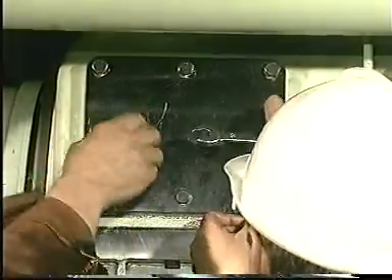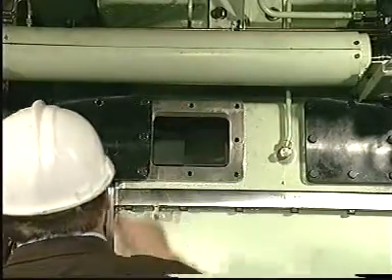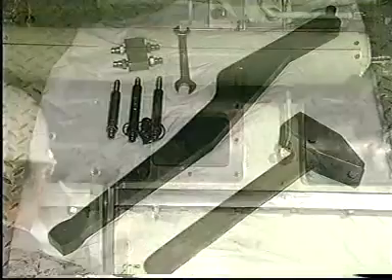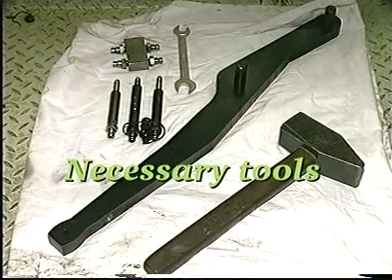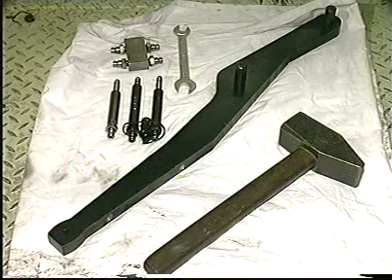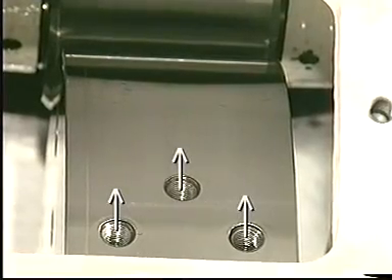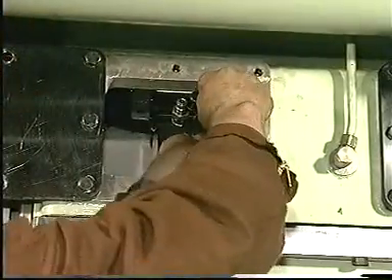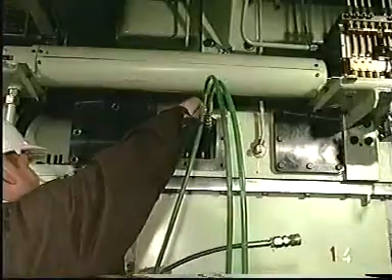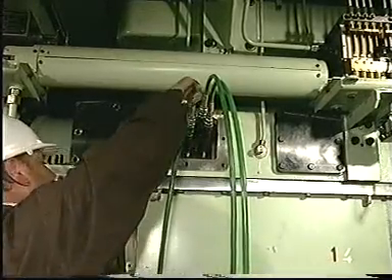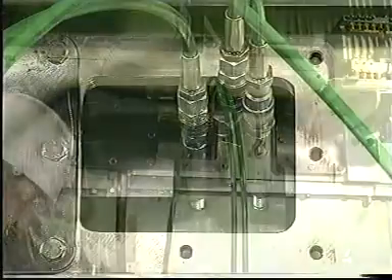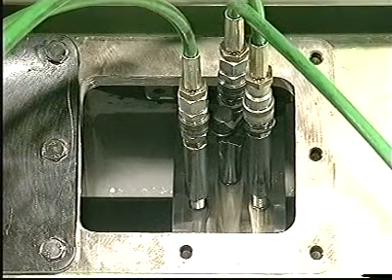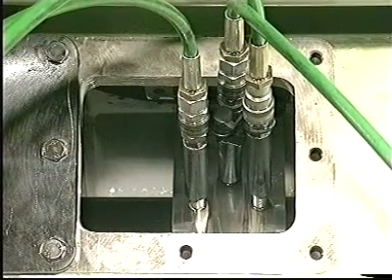If the camshaft has been dismantled or if new cams have been mounted, adjust the cams before mounting the lower part of the camshaft housing. Remove the plugs from the cam and insert copper gaskets. Mount, but do not tighten, the snap-on couplings. Connect the snap-on couplings to the high-pressure pump and vent the system. When oil without air bubbles flows from the couplings, fully tighten the couplings.